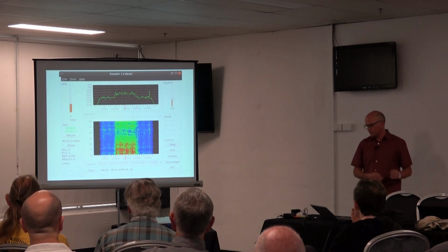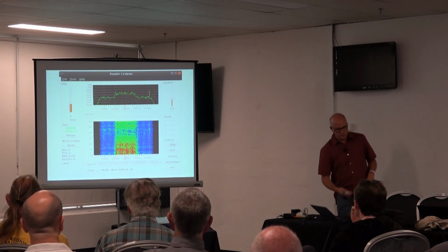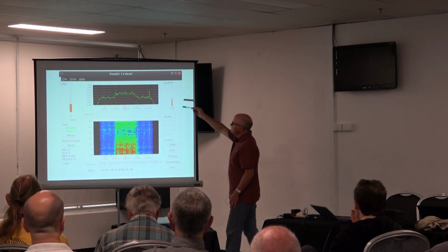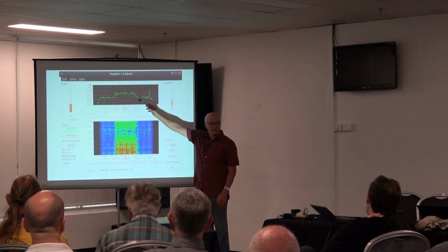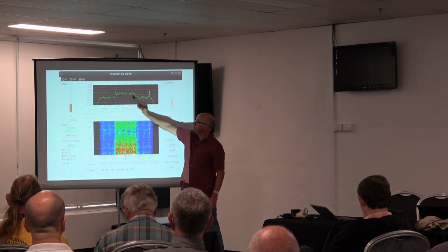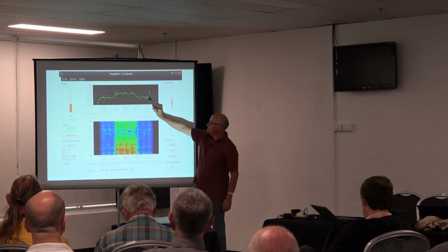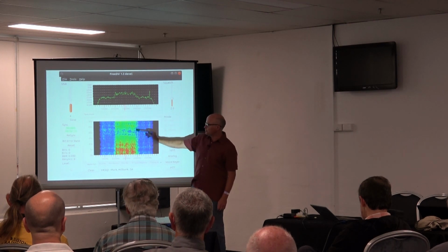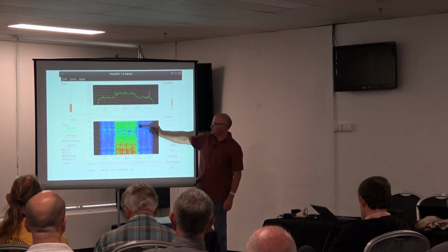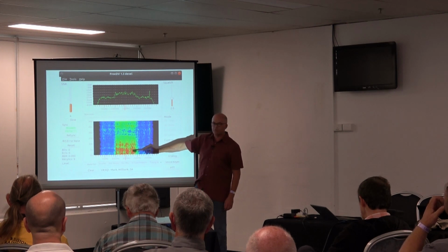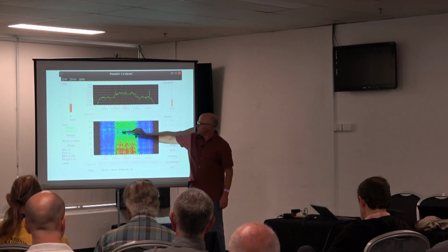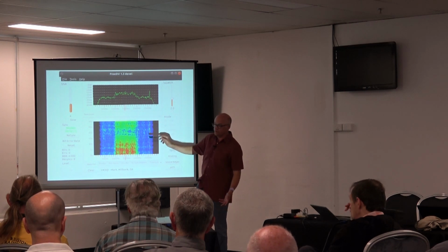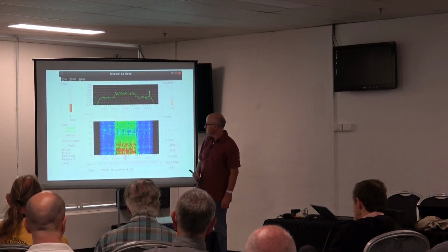This is what it looks like when it's running. I'll just use this pen, but certain things of the window here: this is the spectrum that's being received off air. So this is the FreeDV signal in here. And that's just an interfering carrier that's not interfering with us. This is a waterfall display. This was over a HF channel, so the signal was coming and going a bit. The red is the strong signal. This is where we lost it for a little while, and that's that interfering carrier over time, which the signal ignores. You can't hear that.